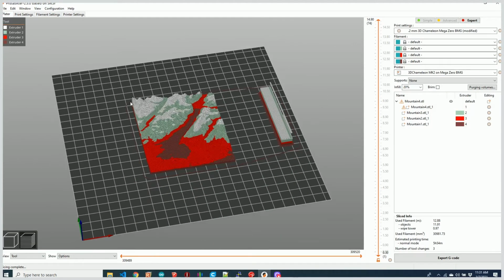That puts the nozzle right in the middle of the build plate. So what's going to happen here is when it's printing, when it wants to change the colors, it's going to move over here to the middle of the build plate. On the y-axis, it would move it over to here, right? On the x-axis, it would move it over here because that's saying the button is over here. And technically, it's actually going to be on the front on the y-axis. We just want the nozzle right in the middle of this purge block, right? So basically, we're going to move it past it.